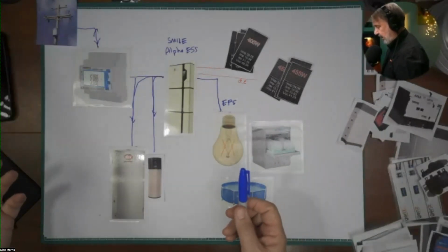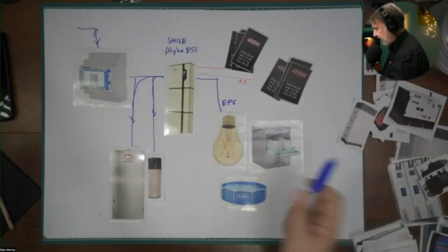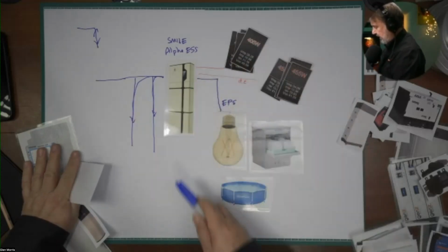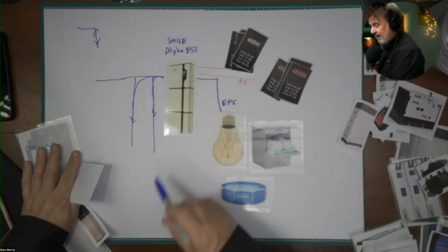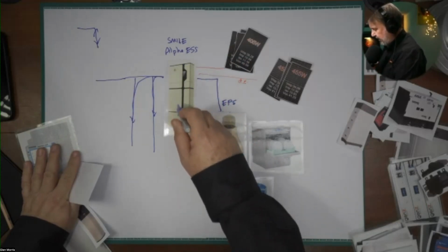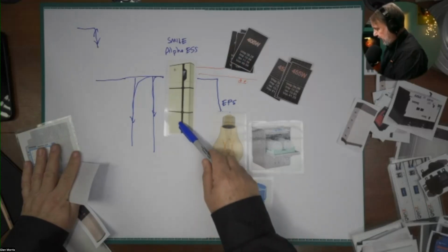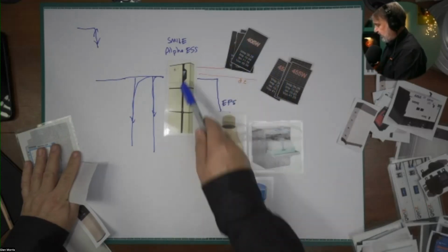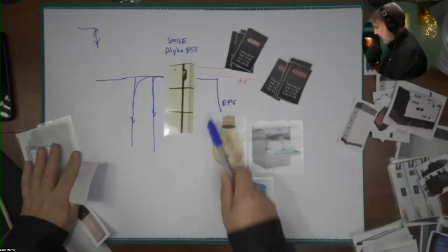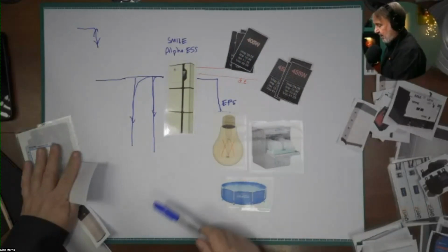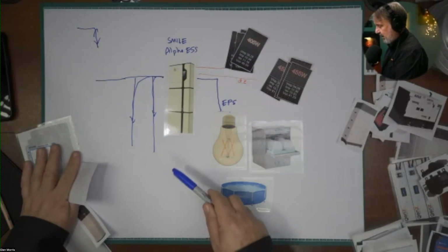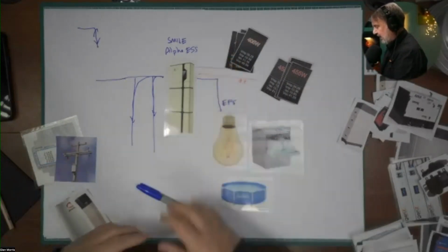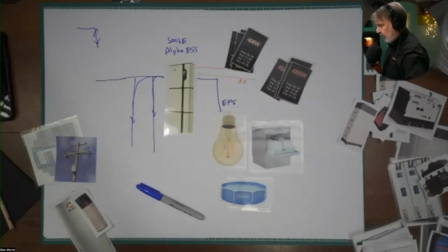But if there's a grid outage and we lose the grid, these will go off, but this keeps working. And this is where a big plus comes in. A hybrid inverter that is internally DC coupled. That means its internal batteries, which are these 2 battery modules at the bottom here, they're 10 kilowatt hours each, are charged from these solar panels even when the grid's not there. So without the grid, we still are getting solar power, charging our battery, and we're supplying our essential circuits. And best of all, from an installation point of view, it's all in one thing. It's an all-in-one solution in this case. You can have hybrid systems that have separate battery and hybrid inverter, but the offer is all-in-one.